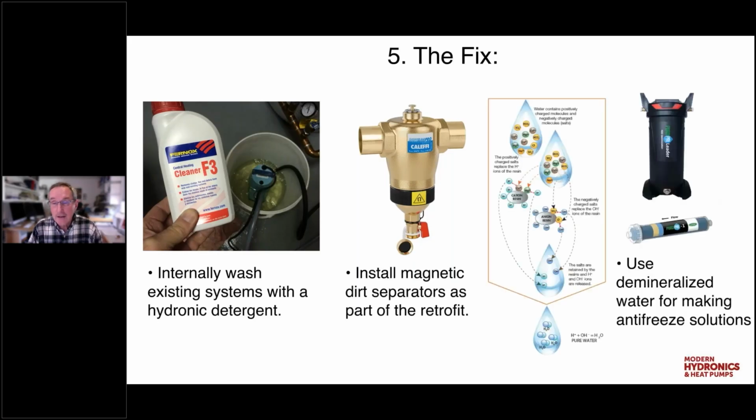And then finally, I'd highly recommend when you're using antifreeze, if you're setting up one of the air-to-water systems and you're going to use an antifreeze solution, the chemistry between the existing water in the system, or even new water, and the antifreeze needs to be correct. And the best water to mix antifreeze solutions with is demineralized water. And what a demineralizer does is it strips out some of the salts that come with groundwater, calcium, magnesium, and so forth. These are dissolved ions that are in the water.